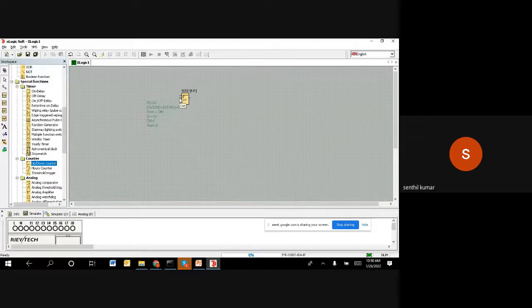When you connect that, every time it passes from 0 to 1, the counter will count the value, and then it will display how many items have gone. This is like a direction. Remember, as we said, one counter can be used as an up counter or a down counter. Up counter means it starts from 0 and goes 1 2 3 4 5 6 7 8, like this. Whereas a down counter, you will have, like, 50, and from 50, 49, 48, 47, it starts from a big value down to 0. That way also you can configure it.